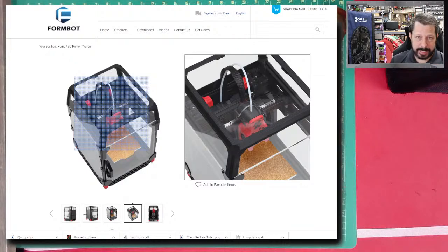There's extremely high speed printing. Now this one is going to be a little bit slower speed, I believe, than the full-blown Voron bigger 300 millimeter printers or whatever. But I don't know that. I'm just assuming that it'll be a little bit lower speed. For one thing, I'm not going to put some of the high flow nozzle stuff on here, so I know it'll have to be a little slower.